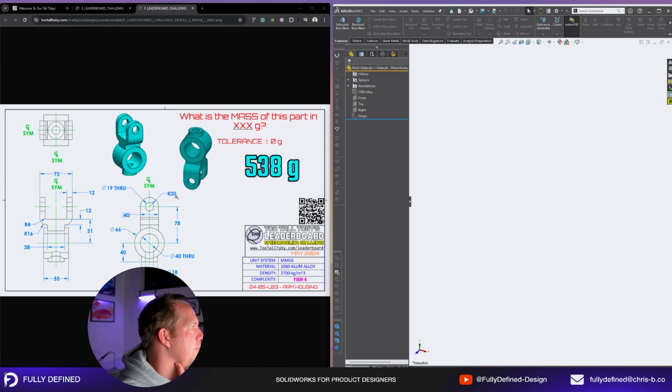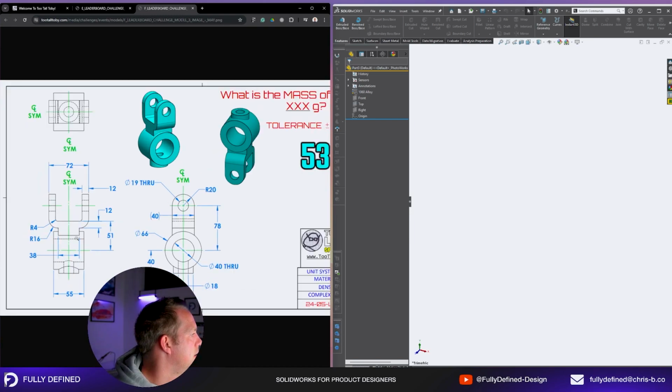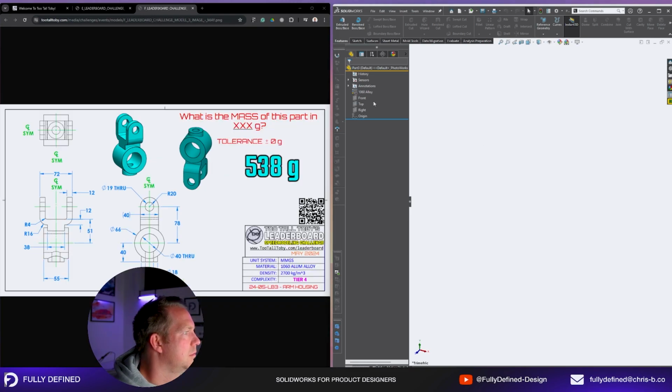I think that circle on the bottom becomes the last element that you do. The way that these shapes go, like that hole's going through, but this section here is merging with this face around here. So you might extrude this circle first, go through, and then extrude that down. Yeah, you can see on this area here, it doesn't pass through that face. So if you sketch it underneath and just merge it all the way through, that'll be fine. So it's good to go.